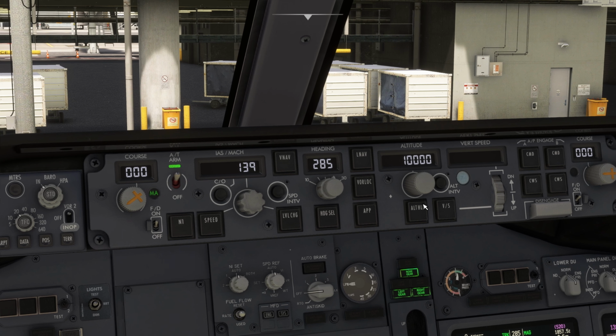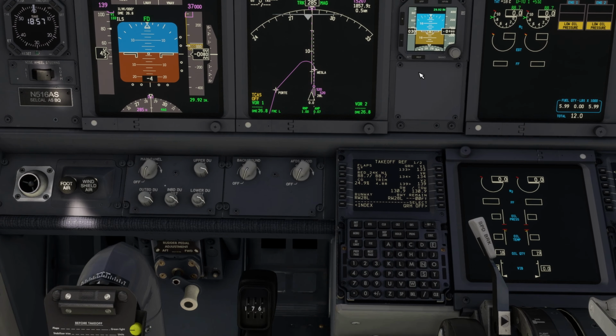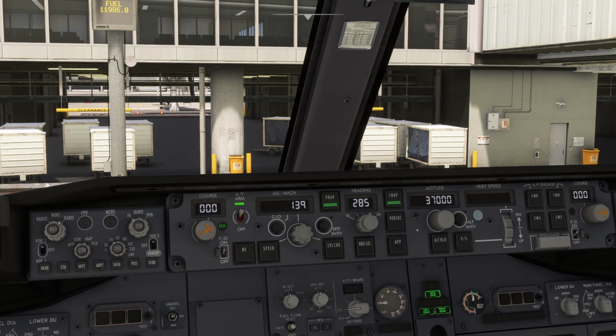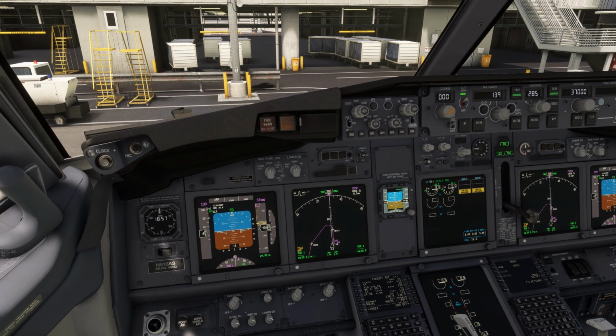That's great. And we're just going to select the altitude, the cruising altitude, just to simplify things. If you're flying on VATSIM, then they'll just assign you an initial altitude. But we're going straight up to cruising altitude, because we want to keep things simple. We're not using ATC right now. So that's all good. VNAV, LNAV, both on. Both should illuminate if you did everything correctly in the FMC. By this point, the autopilot panel has been effectively set.